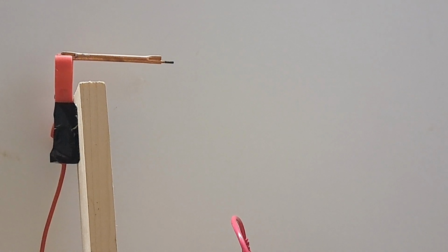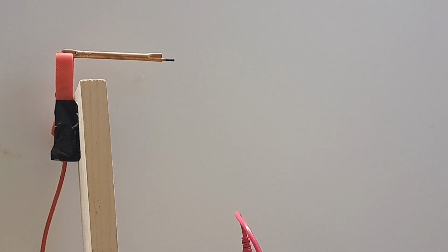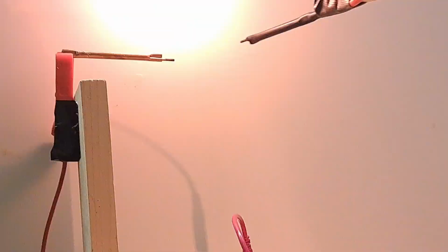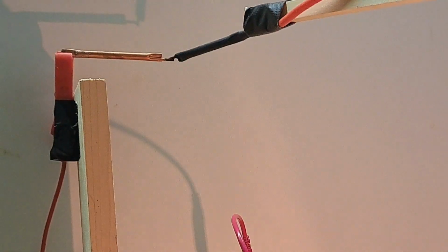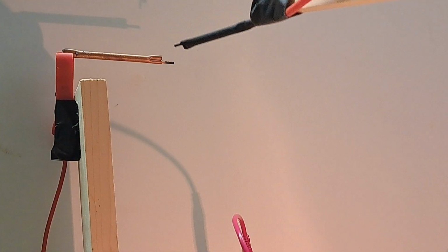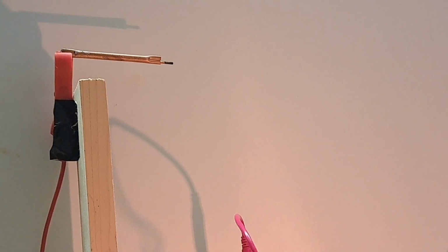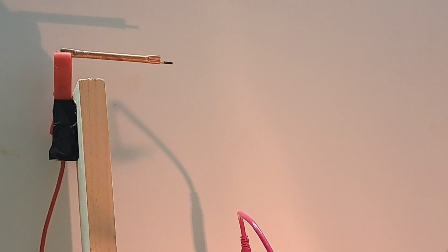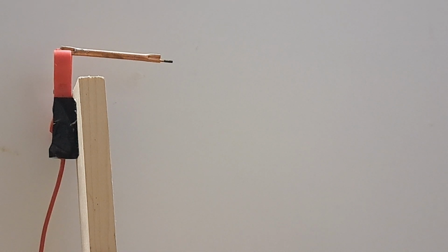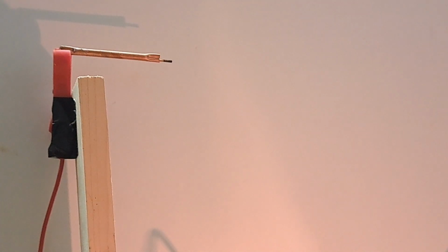This is now without resonance capacitors, as we're looking at the 0.3 amps with the 5.5K resistance. So not too bad, but not what we want. So this is now with 3 resonance capacitors, as shown in the calculations. We should get around 3.5 amps of current on the secondary side. Let's see how that looks.